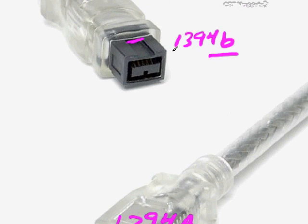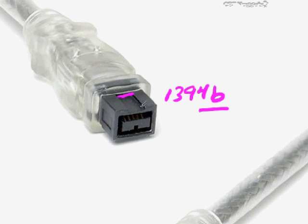And then another kind of cable you might see looks amazingly like this. It's almost identical to this 1394B look that we have, except that the notch, the key up here at the top, is actually a little bit wider, and that would be what we call a 1394B beta cable. And that means that it will only communicate with other 1394B devices or ports.